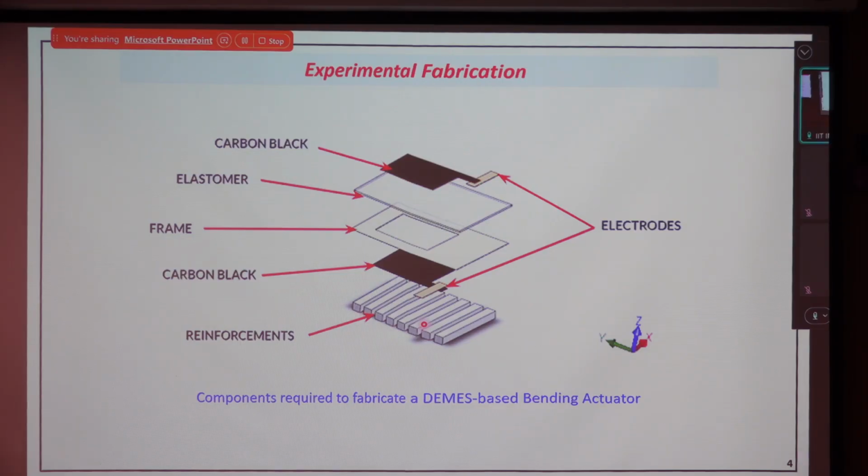That orientation can be 30, 45, 60, you can vary it. Initially it will be at 90 degrees. So along with the bending modes, we get twisting modes of deformation, and you will see that in practical applications if you biomimic the response of some flapping wings.